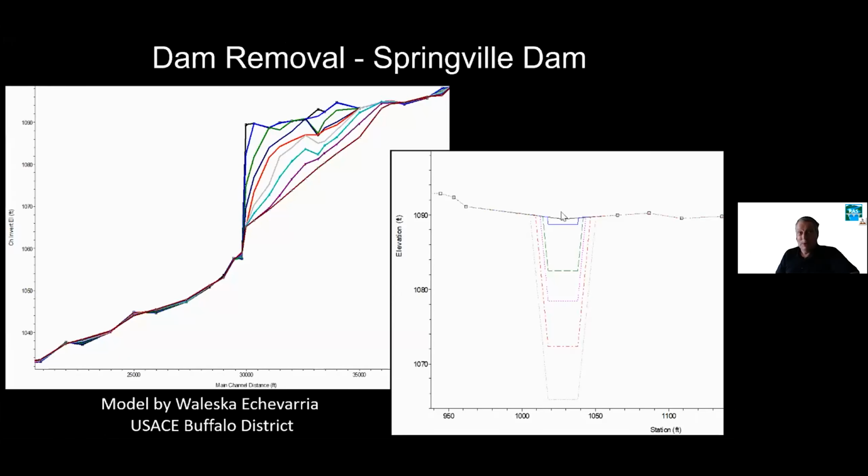But one of the problems with dam removals is that you can't calibrate them. They're novel events. And so we don't want to deliver a model that's uncalibrated. And so what we did here is, instead of delivering a model and saying, we didn't calibrate this, but it's right, we did sensitivity analysis. And so we didn't say that it's going to take 38 days for the sediment to erode. What we said instead is it's going to take months, not days, or days, not hours, but also days, not years. And that's the way that you can constrain an uncalibrated dam removal model.